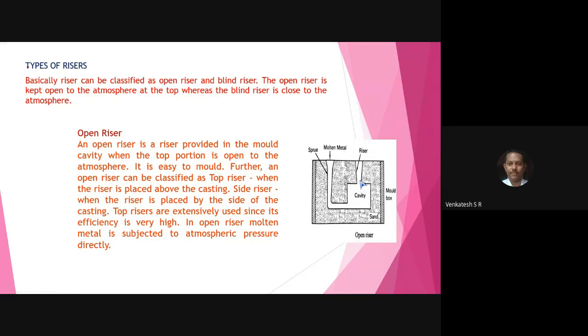As the solidification completes, the mold cavity requires a little amount of liquid metal, which is supplied by the riser to the mold cavity in order to complete the solidification process. Otherwise, there will be a lack of filling of the mold cavity. There will be a problem with insufficient liquid metal, causing non-filling of the mold cavity. Usually 2 to 7% of liquid metal is required for the mold cavity in order to compensate the volume contraction.